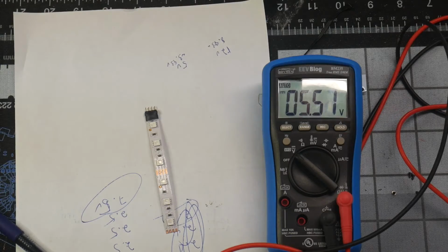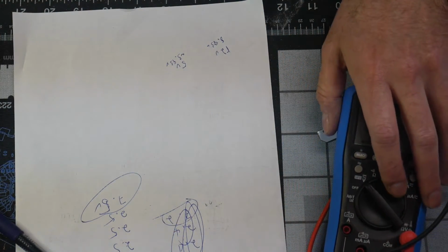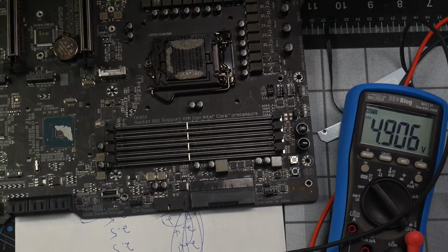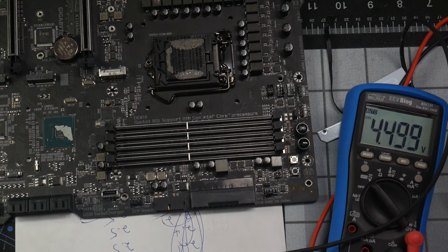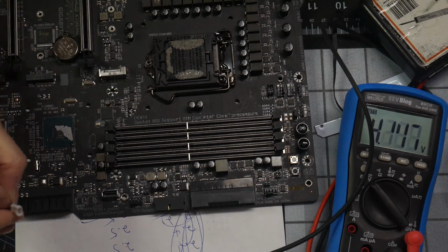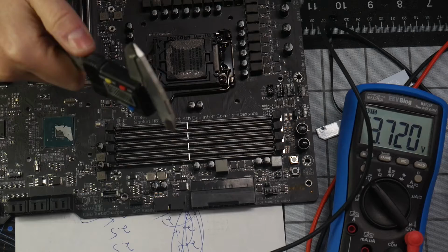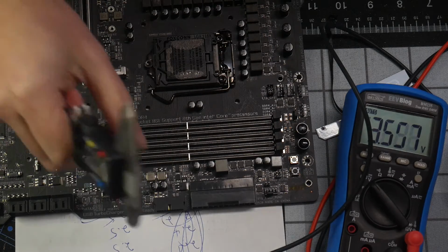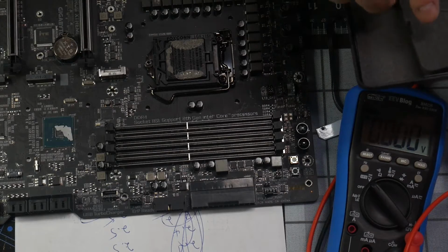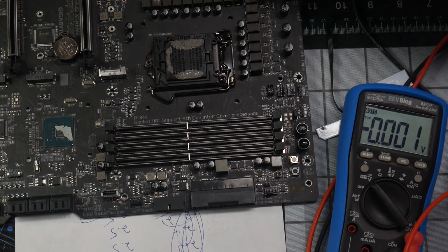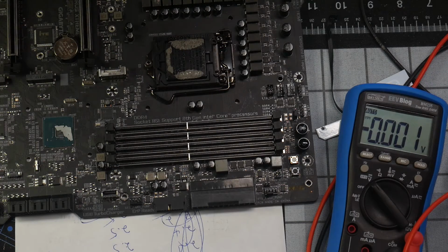I mean, there's also, can't forget about the damn connectors. So the connectors can vary quite a bit. The best way to do it is to get a connector, and the best way to find out what type of connectors you need, like for example this, is to get a caliper and measure it. That's kind of the best way to do this. Again, you have to do a little bit of searching, and a way to verify is to look at the data sheet, if you find a connector that looks like it.